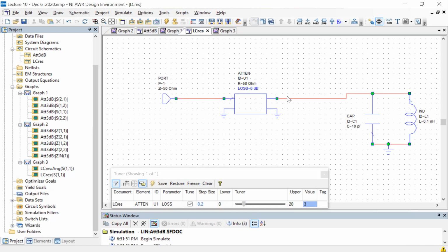Okay, so you will say, fine, I know this, so let me just increase the power I have put in by 3 dB. That will compensate the power reaching the device, but you will not compensate what happens to the power which is coming out in the other direction, right? You're always going to experience 3 dB loss there. So the incoming part can be compensated by putting more power, but the outgoing part cannot be compensated.